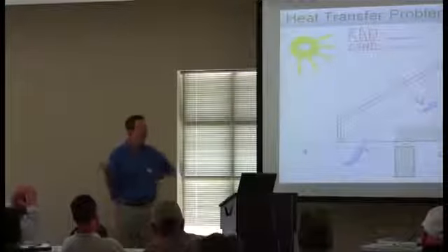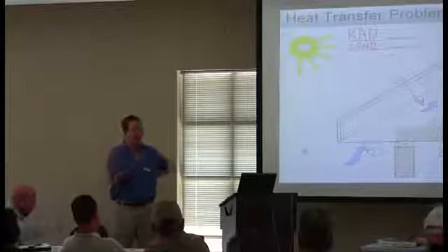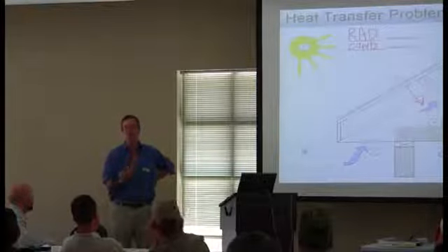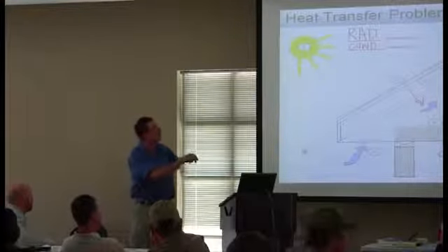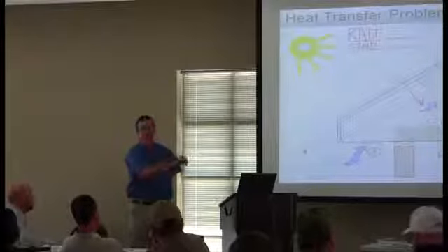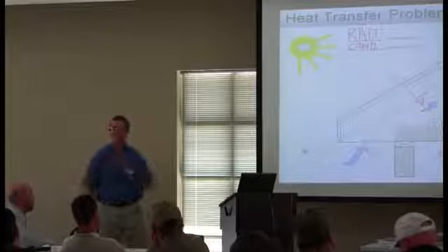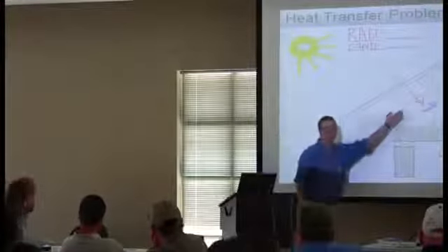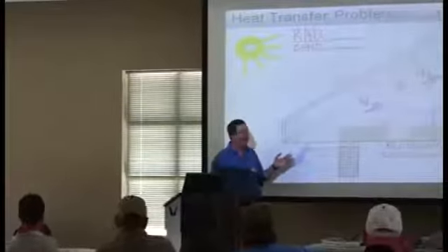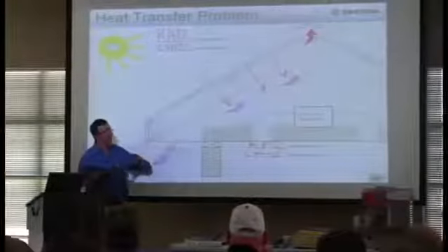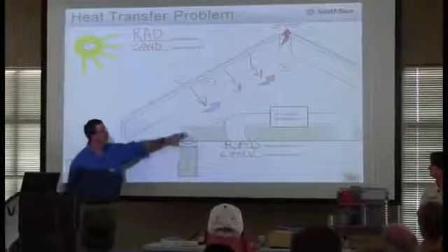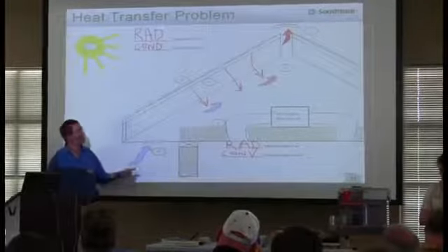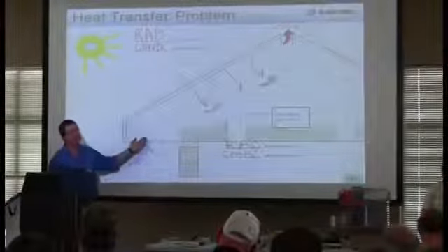Yeah, a metal roof would be a lot less absorptive. Certainly not without cost implications. I'm not trying to imply that, but it would do a lot better from a heat absorption standpoint. Or we could put a low-emitting surface here, such as the solar board product, that would not emit heat by radiation. And then just appreciate that venting an attic is treating the symptom. I'm not saying it isn't a good thing to do in this situation, but with venting attics, I think we get all excited about thinking it's the greatest thing in the world. In reality, it's just treating the symptom.